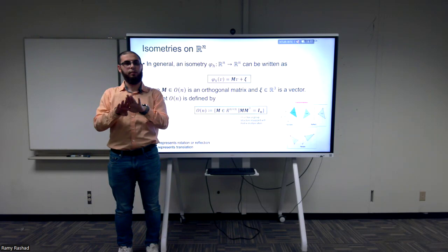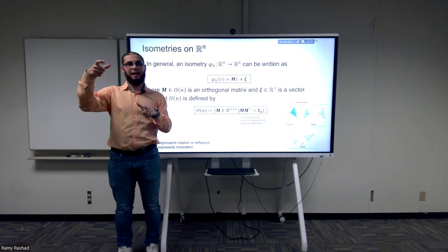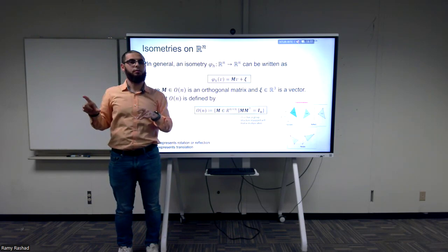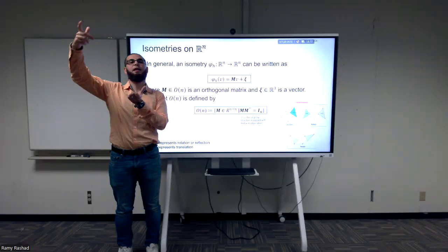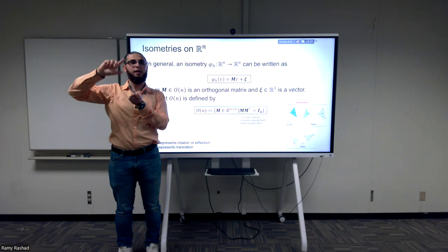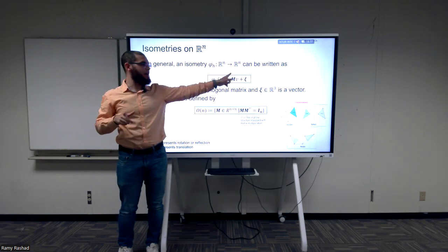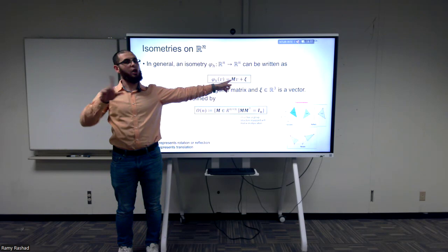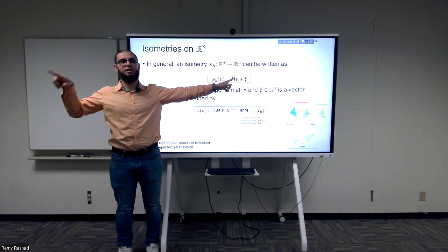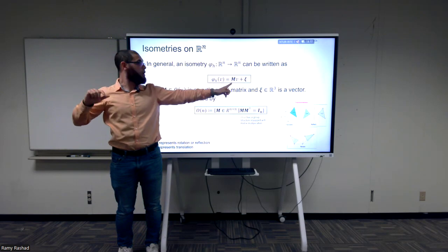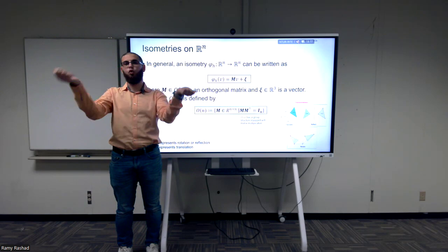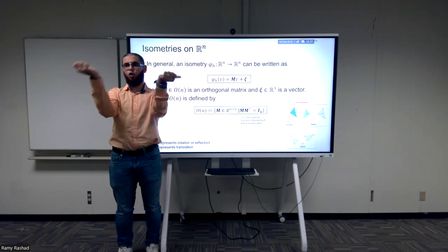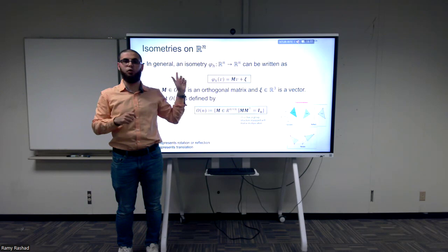They're 1-to-1. The problem of Euler angles is that they are only a chart. It's not a 1-to-1 representation like that, and this is where the singularities come in. Same with quaternions. Quaternions represent rotation matrices, but not in a 1-to-1 map. They don't have an injective map. I can give you one rotation matrix and you can represent it by 2 quaternions, and usually they are the opposite of one another. So they are not 1-to-1.